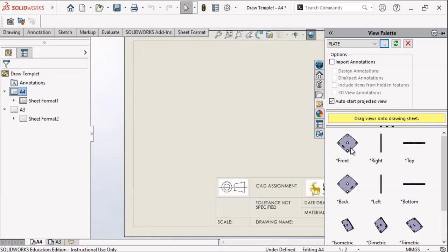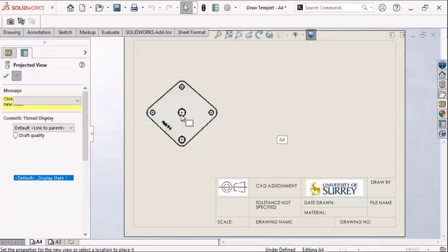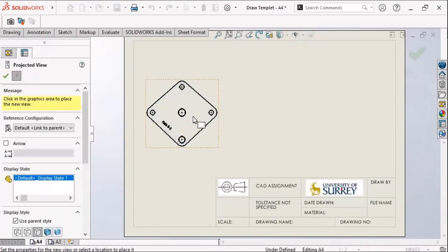Okay, assuming you have done adjustments and you want to bring this front view in, then you can click and hold the left mouse button, and drag it to the paper and release. Then you can move your mouse sideways without holding the mouse button down. And then once the end view is at the appropriate position, you can just click and release it.